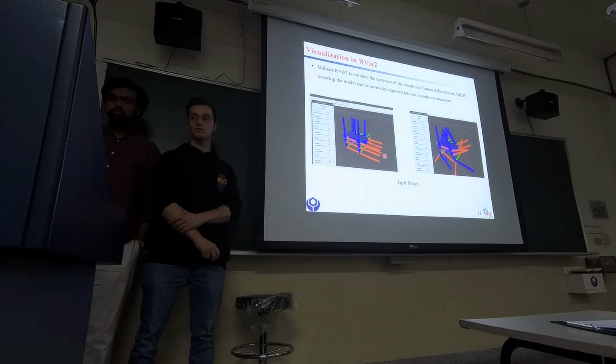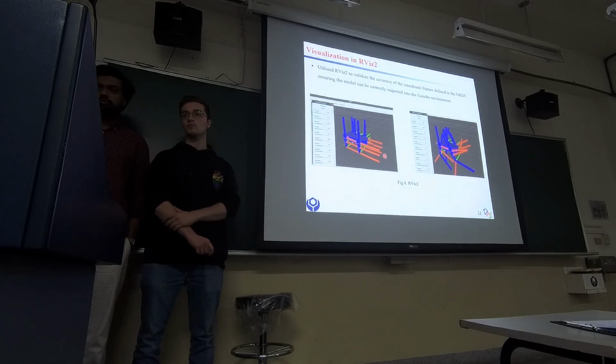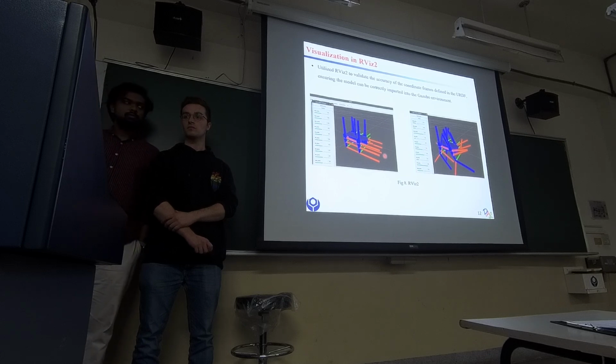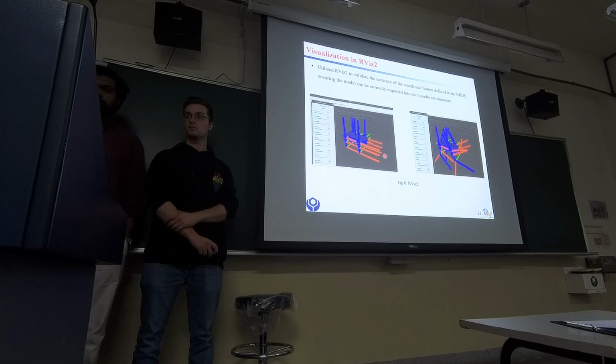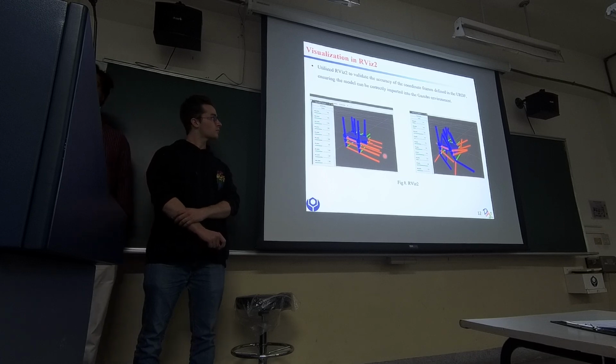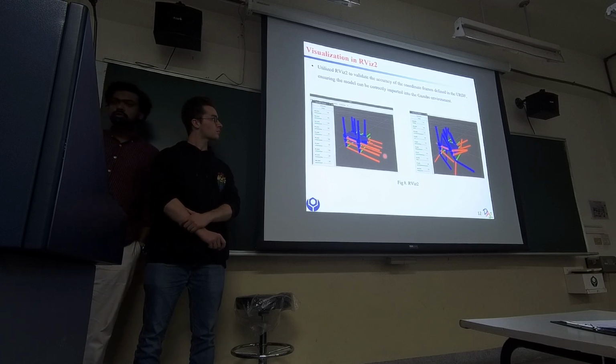After completing the URDF, we import the model into our URDF tool to make sure the coordinates defined in the URDF were correct. This step ensures that the correct model can be imported into Gazebo. We can see the picture on the left-hand side. All coordinate points are in the correct direction when positioned at the origin, indicating that our settings are all correct. And the right-hand side picture shows how we use the RViz slider to test the movement of the joints and the coordinates we designed, ensuring that everything was properly correct.